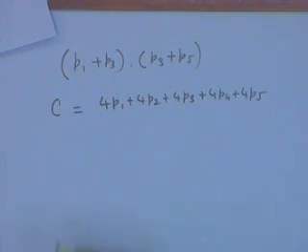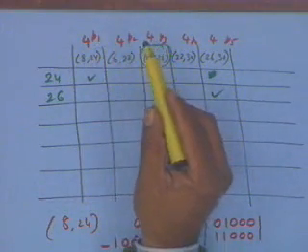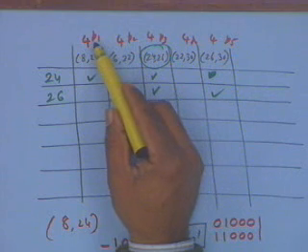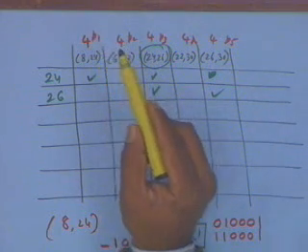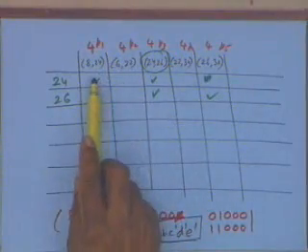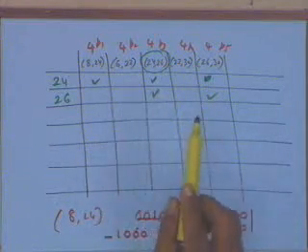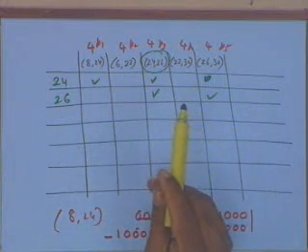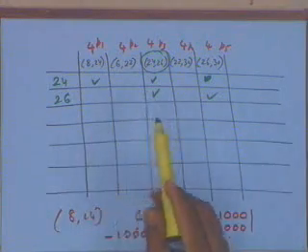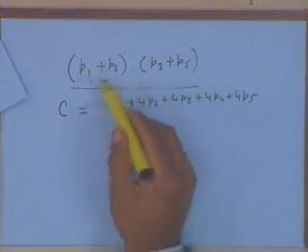So what I am saying is, if prime implicant P1 is present in my final solution, then P1 is 1. If it is absent, it is 0. So I have 5 implicants over here, 1, 2, 3, 4, 5, all of them of course prime implicants. None of them is essential. Essential ones I have already eliminated. These are all non-essential, and I have to choose a subset of them. So choosing a subset of them is nothing but solving this equation.